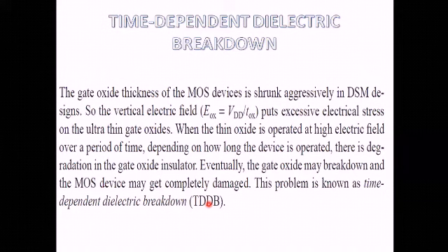So these were in short the small geometry effects, the narrow channel effects, and also the short channel effects. Mainly all these things occur due to scaling. Due to scaling, the MOSFET dimensions are excessively shrunk. This includes the small geometry effects, which introduce potential problems in the device characteristics and also in the modeling of these effects. This scaling is what gives rise to the short channel effects, narrow channel effects, and small geometry effects. So you can see how these are permanently degrading the device characteristics.